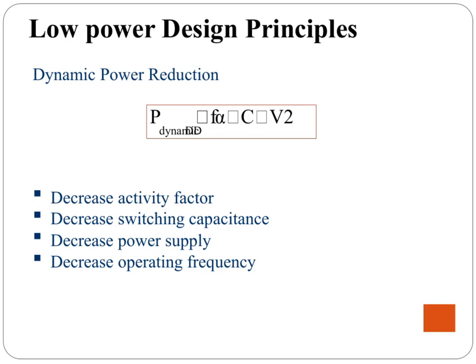Now, let's dive into the key principles behind low-power design, starting with dynamic power reduction. Dynamic power is governed by a simple but powerful equation. Power equals the activity factor multiplied by capacitance, voltage squared, and frequency. Each of these components offers a lever to reduce power consumption.